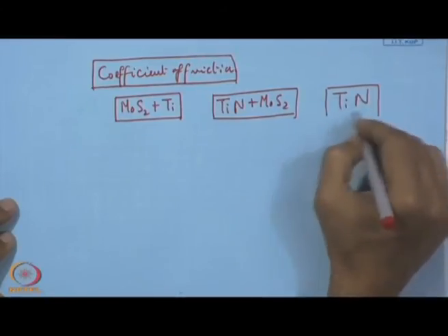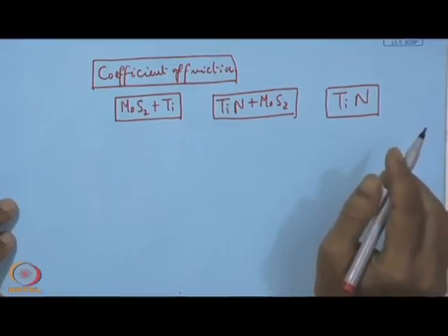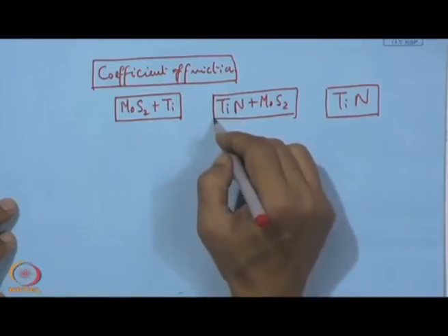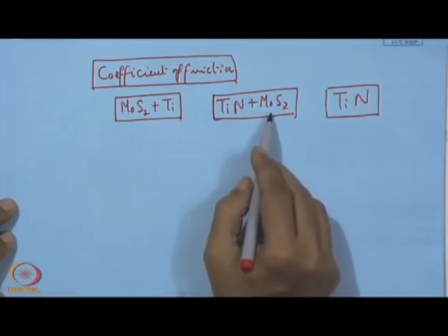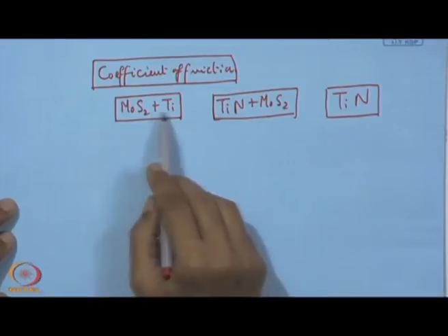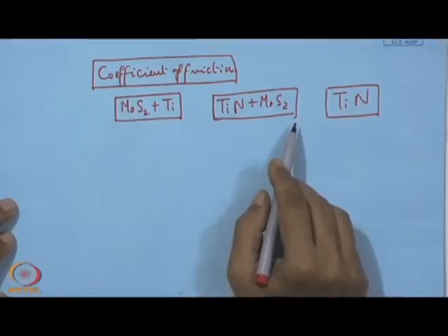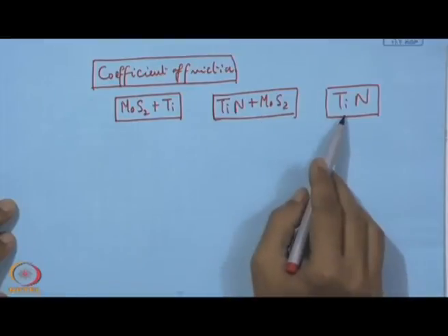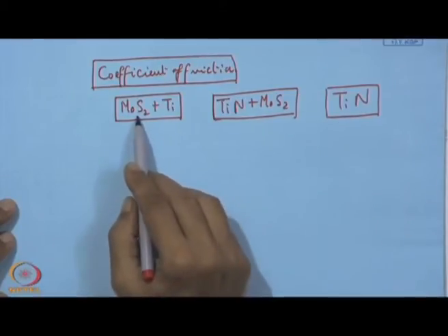However, if we consider both wear resistance and coefficient of friction, then the right blending between titanium nitride and MoS2 would be one of the right choices in that direction, and accordingly that coating can be ranked as number 1 in this family, which can give a hard-lube property, meaning the hardness of the titanium nitride and also the lubricity of molybdenum disulphide.